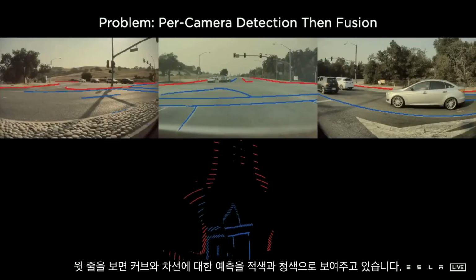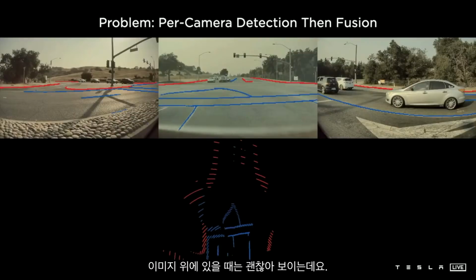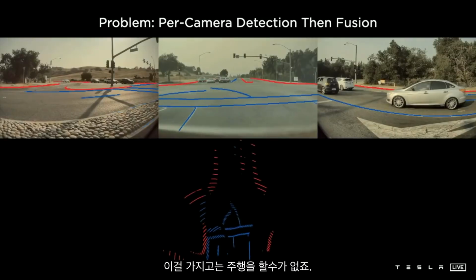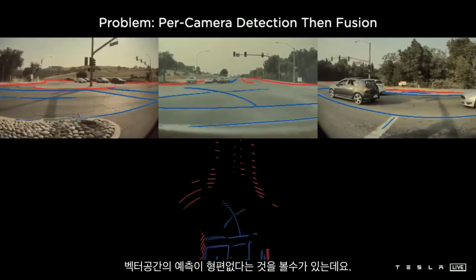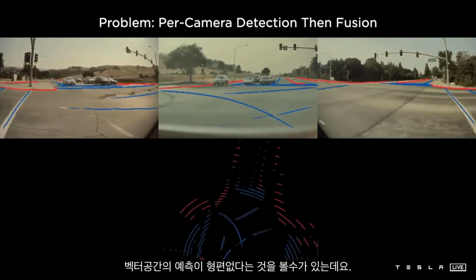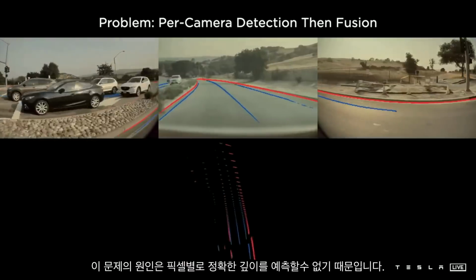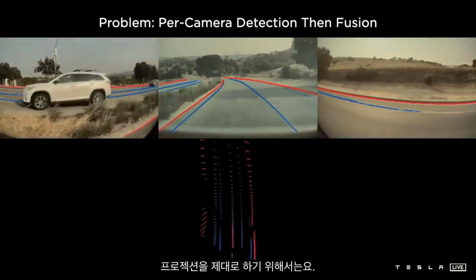Here I'm showing on the first row the predictions of our curves and our lines in red and blue. And they look great in the image, but once you cast them out into the vector space, things start to look really terrible. And we are not going to be able to drive on this. You see how the predictions are quite bad in vector space. And the reason for this fundamentally is because you need to have an extremely accurate depth per pixel in order to actually do this projection.